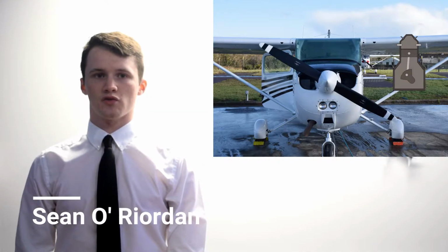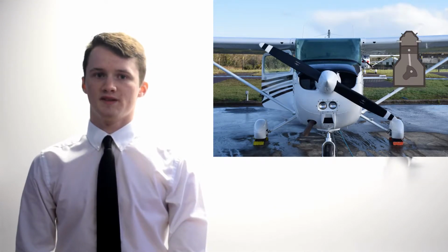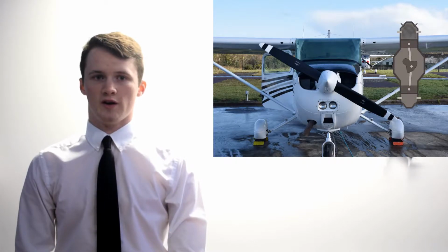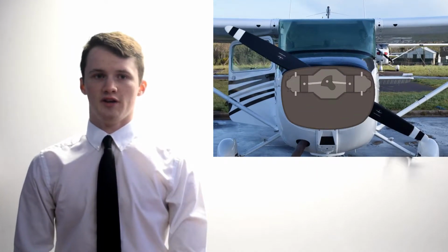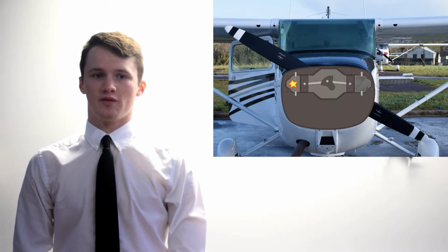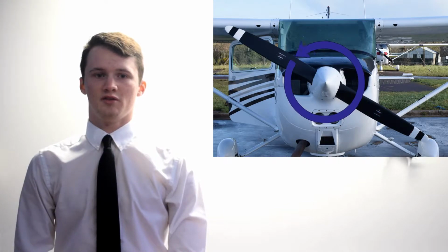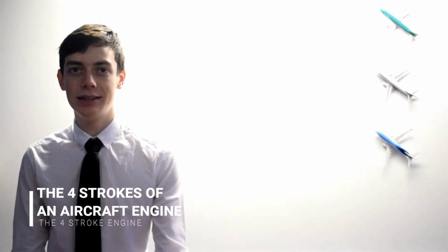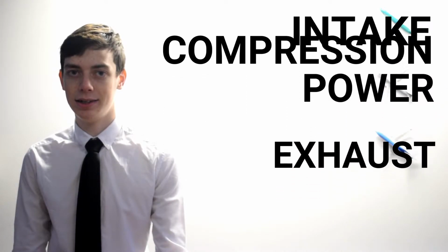A spark ignition four-stroke engine, also known as a four-stroke piston engine, is mostly used in small aircraft. The engine converts chemical energy, such as fuel, into mechanical energy that takes place within the cylinder of the engine. There is a repetitive up and down or back and forth linear motion of the piston that produces mechanical energy to rotate the propeller. In a spark ignition four-stroke engine, there is a four-stroke operation cycle. These four separate strokes are the process of intake, compression, power and exhaust.